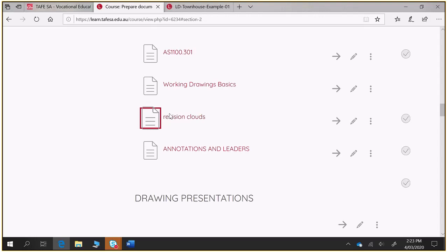But what you don't want happening is that there's a drawing set, particularly after council, which has gone out to builders and for tendering and things like that, and then there's been a revision, and the people that won that tender have got their original set of drawings. I guess that's more to do with communication, but they want to know that if they're on site with a set of drawings that have revision clouds on it, that's something they have to check, to make sure that's what they've planned for.